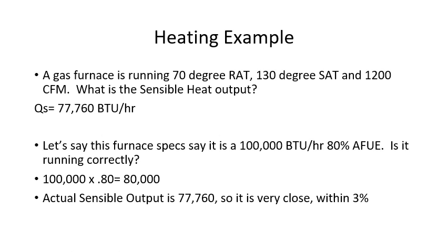And airflow measurement is very hard to be exact in the field as a technician. The instrumentation that we carry in the field to measure airflow is good, but it's not laboratory quality. So we could be a little bit off. If you're within 5% of what your specified number is, that is acceptable and there's no reason to be alarmed. In this case, we're within 3%. So we're going to move on to our next check.